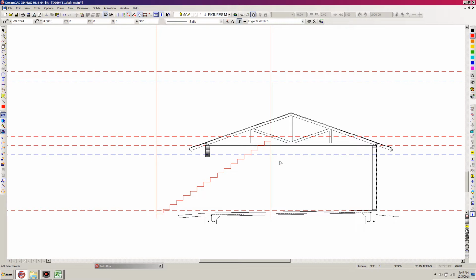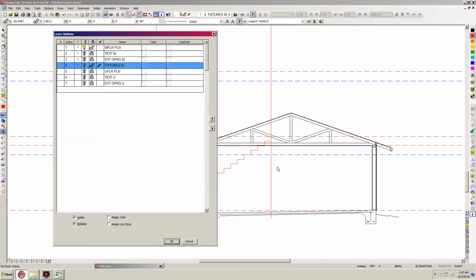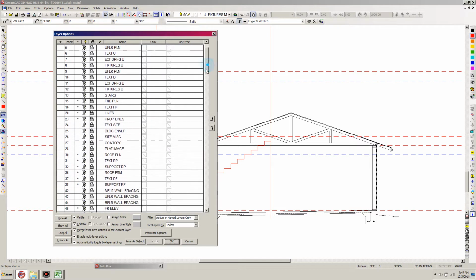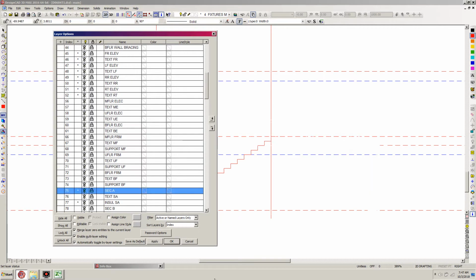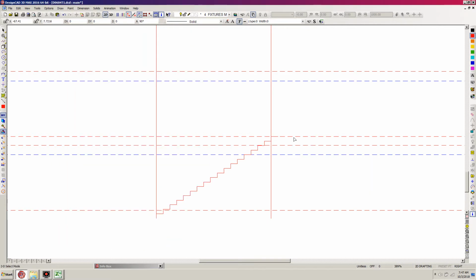Okay, so now I'm going to temporarily just hide layer 75, which is our section. Okay, so we can make sure that this last one actually ends up at the finished floor level, or actually very close. I hit V for vector and just K, and then go out of orthogonal mode and go here and gravity move, and you can see here it's -0, so it's really close.